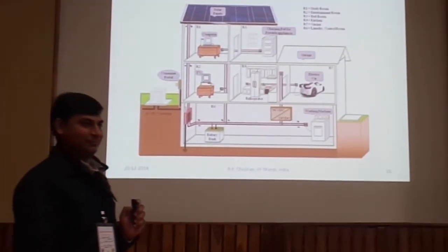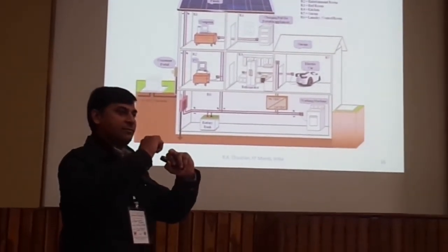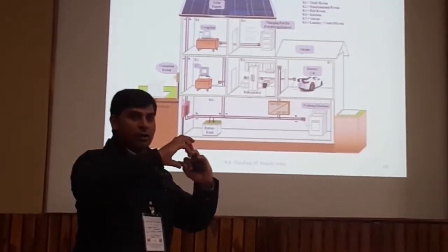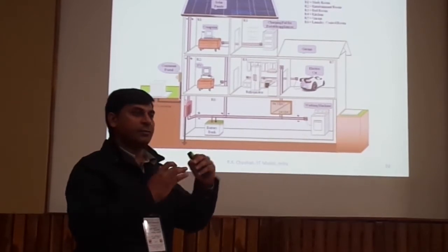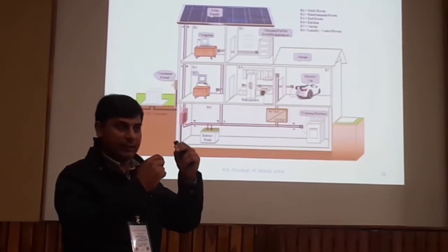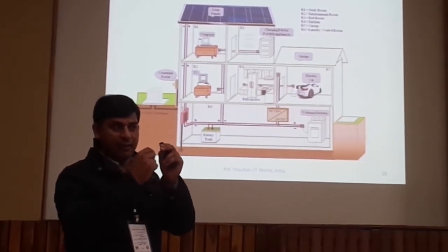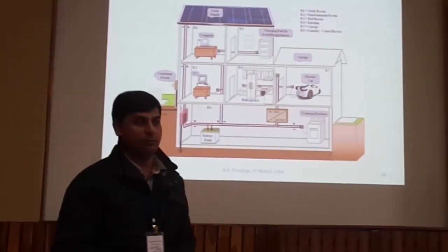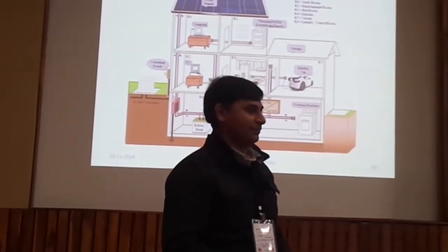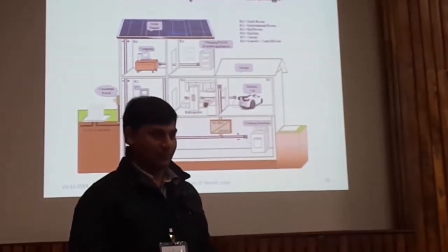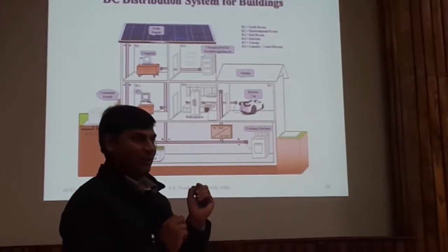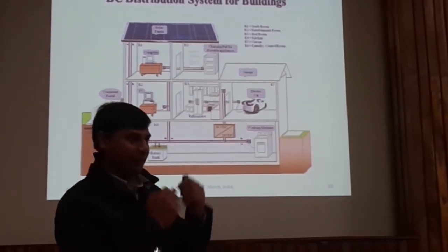Unipolar means we have a 3 wire system in which, if we connect the load or source with positive and negative, it will be 24 volt. If we connect the load or source with positive and neutral, or negative and neutral, it will remain 12 volt. With respect to ground, you connect something to positive or to negative. Yeah. And if the voltage rating is high, like 24 volt, then we connect it with positive and negative.